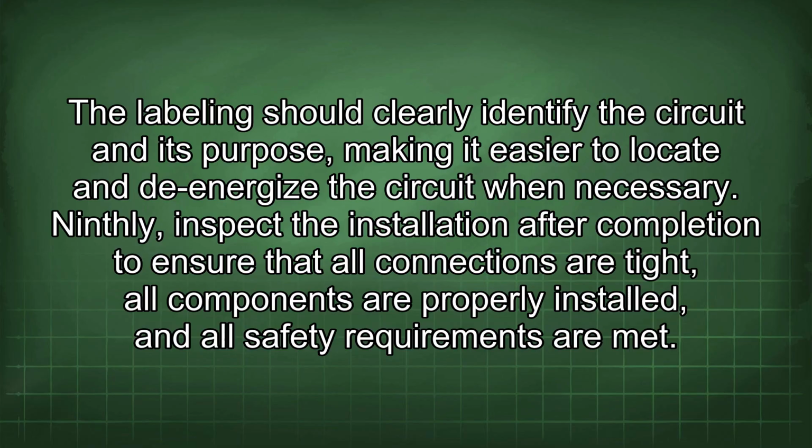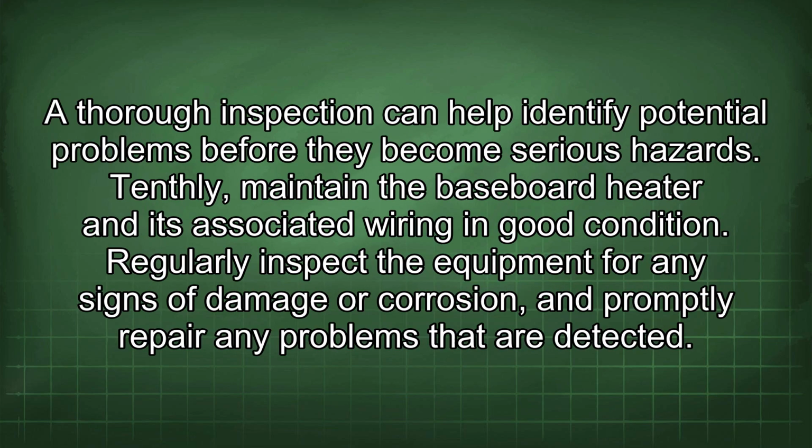Ninthly, inspect the installation after completion to ensure that all connections are tight, all components are properly installed, and all safety requirements are met. A thorough inspection can help identify potential problems before they become serious hazards. Tenthly, maintain the baseboard heater and its associated wiring in good condition. Regularly inspect the equipment for any signs of damage or corrosion, and promptly repair any problems that are detected.